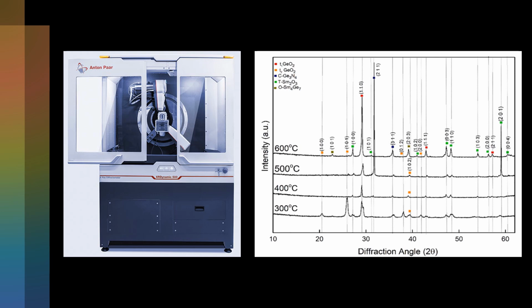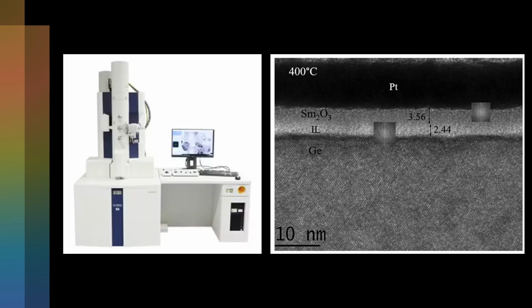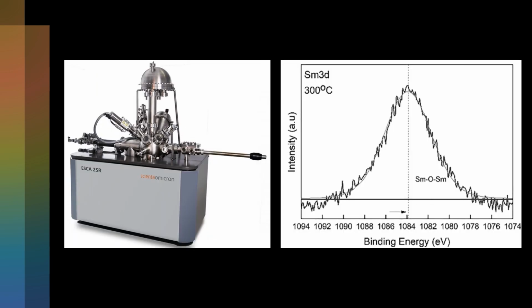The fabricated devices are then characterized by X-ray diffraction, which showed formation of trigonal samarium oxide. The devices were imaged using transmission electron microscopy, which showed a thin samarium oxide dielectric with an interfacial layer containing germanium. Small thicknesses of 4.3 to 6.9 nanometers were obtained. From X-ray photoelectron spectroscopy, we observed that germanate structures were formed which suppressed formation of gaseous germanium oxide.